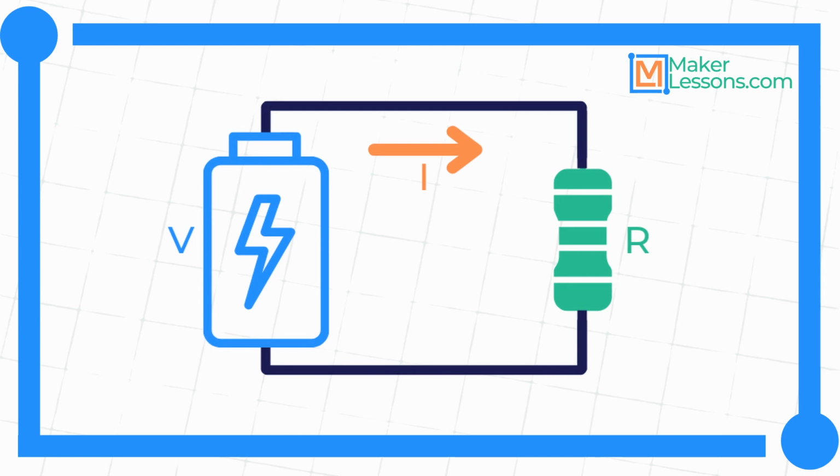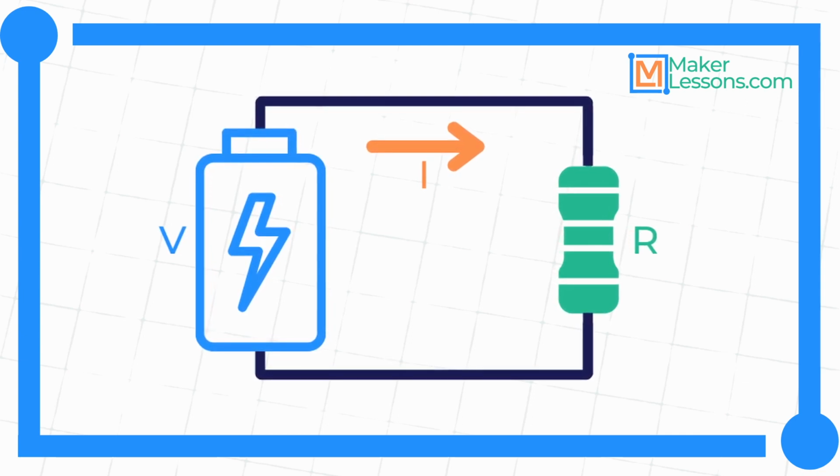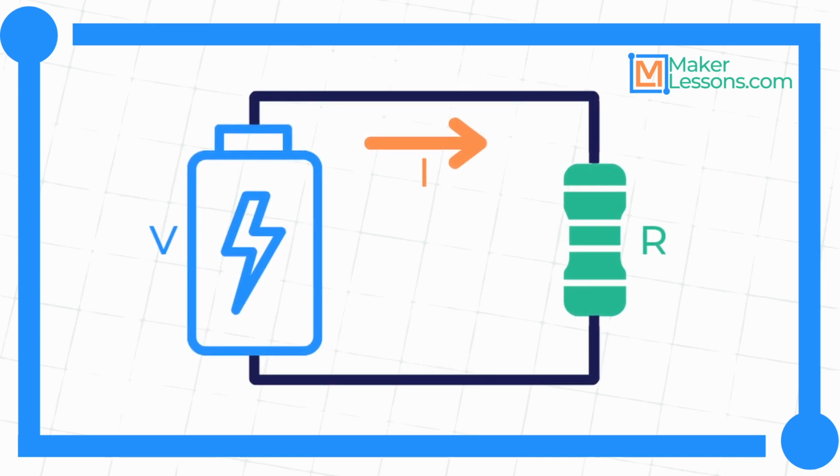Because of this, when defining current on a circuit, the direction representing positive current must be specified, usually by an arrow on the circuit schematic diagram. This is called the reference direction of current.